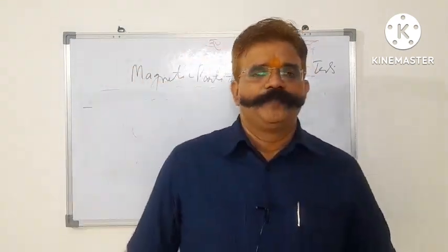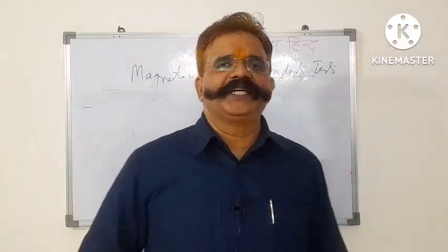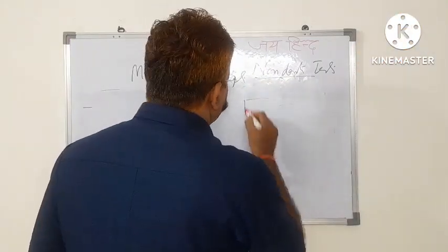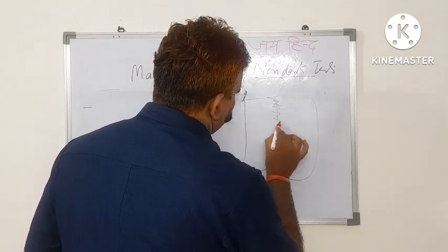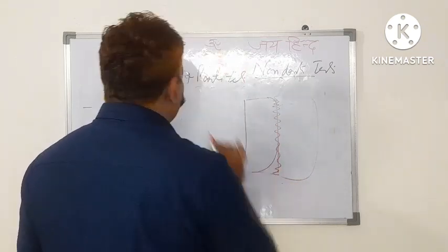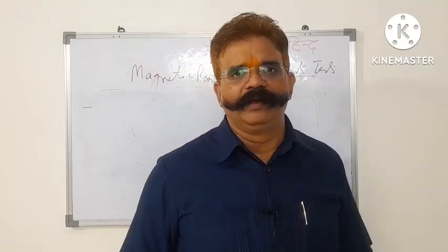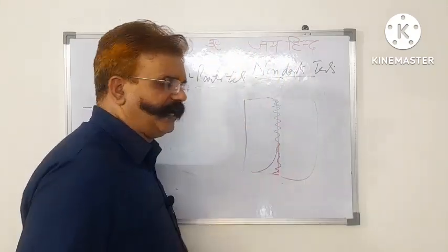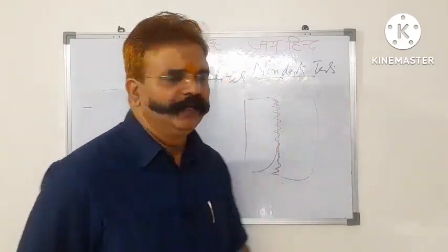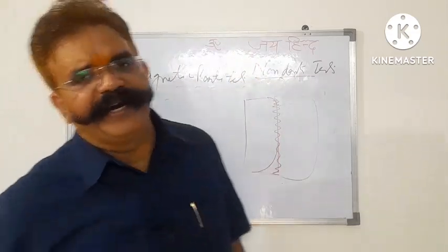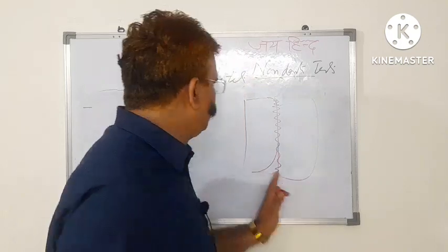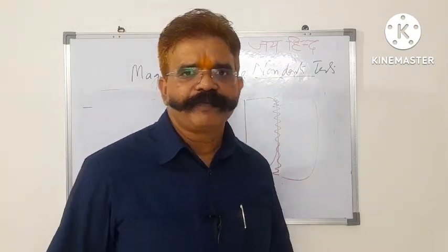Whenever big welded sheets are to be tested, where big sheets are welded to each other, this magnetic particle testing is very suitable, because these big sheets cannot be brought inside an X-ray cabin. These big sheets also cannot be tested effectively with penetrant testing, being rough in shape and size.